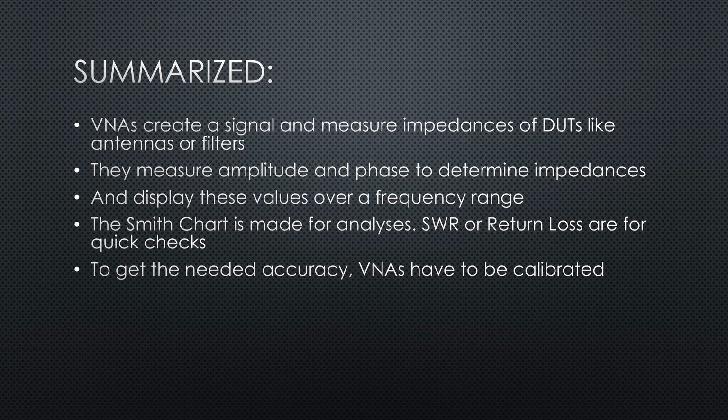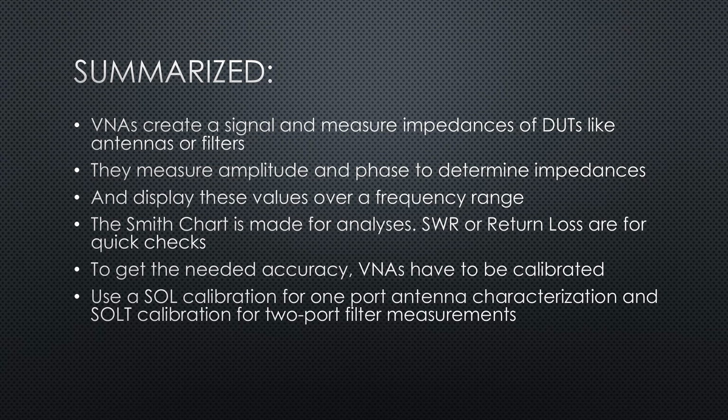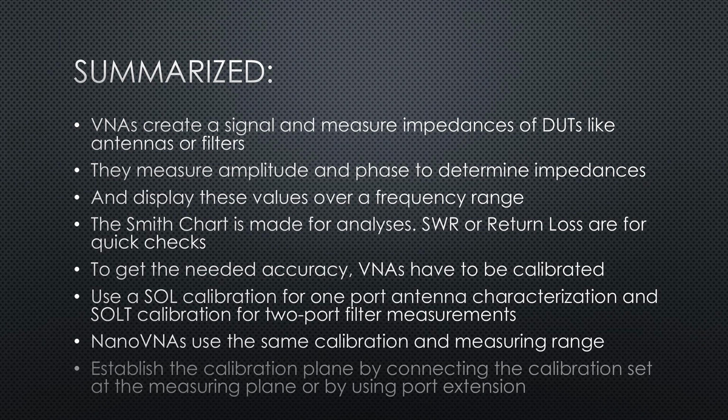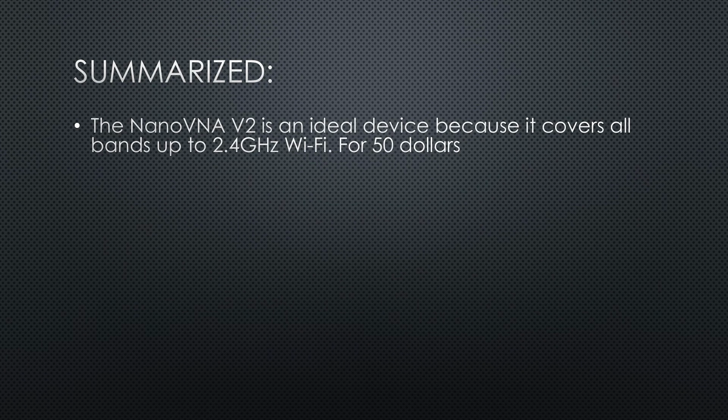To get the needed accuracy, VNAs have to be calibrated. Use a SOL calibration for 1-port antenna characterization and SOLT calibration for 2-port filter measurements. For the NanoVNAs, the calibration range always is the same as the measuring range. Always establish the calibration plane where the measurement is planned, either by connecting the calibration set at this plane or by using port extension.